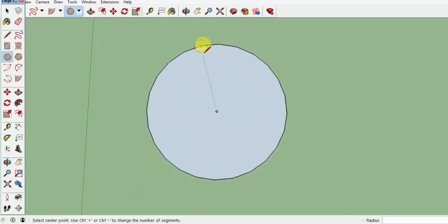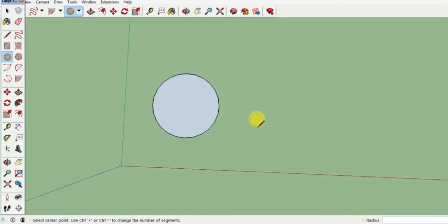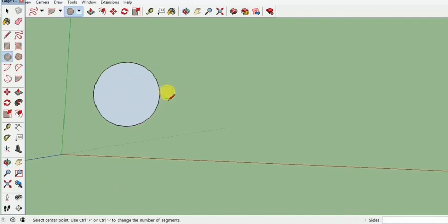But I'm sure all of y'all will be wondering, why is this circle so rigid? As I told you, everything is created out of edges in SketchUp. Now, to create a particular circle, a minimum requirement of the edges would be 24 in number. So 24 lines are required to create this circle. As you can see, if I press escape and I go back into my circle, initially, before I even give its single click, it asks me for the number of sides over here. At the moment, you will notice that the sides are 24, which is why we had a rigid circle.